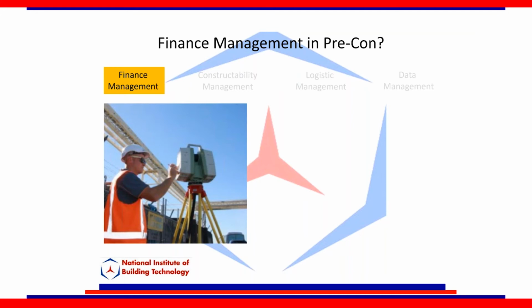The theory is you create a map of every single building that you are trying to do as-built of, or retrofit. You take that data and create a model, or you can leave it as a point cloud model. Then when you start designing, you know exactly what is there because you already scanned it, and you can start connecting to those existing conditions versus coming with a blank slate or going with your measuring tape and taking photographs every time you go there.